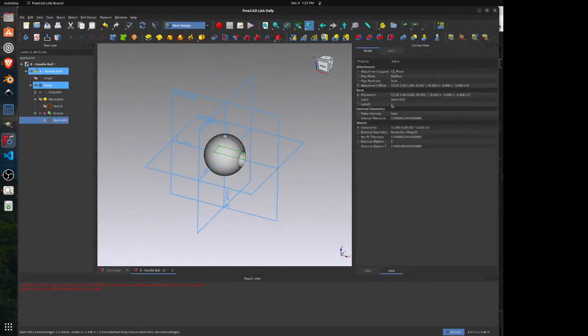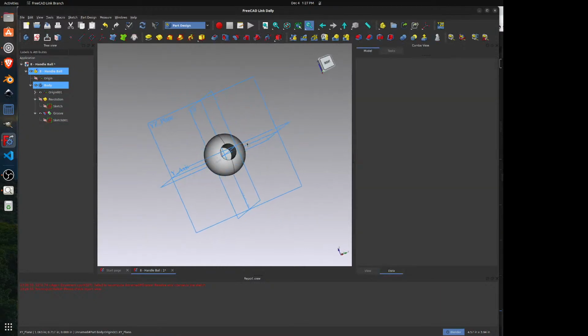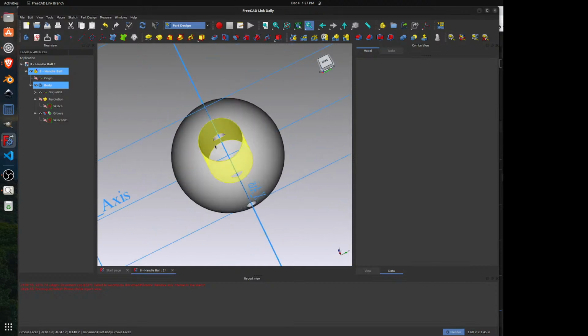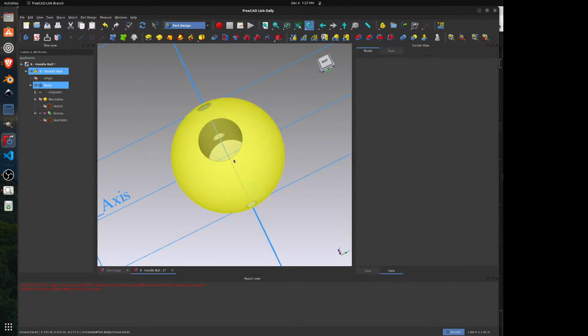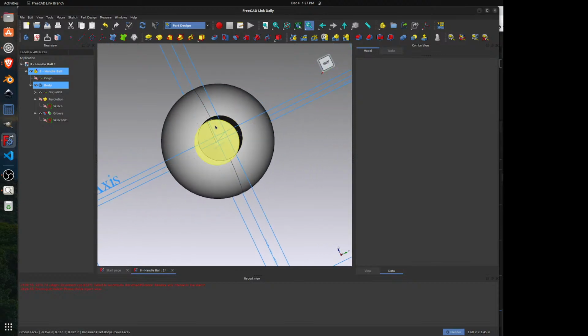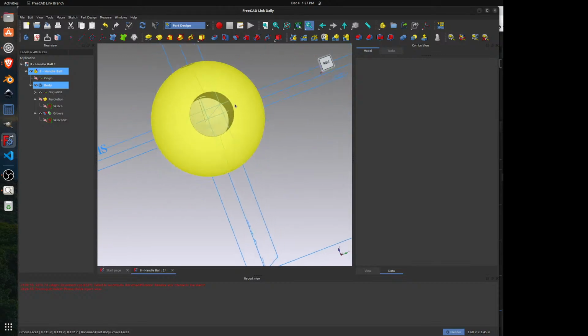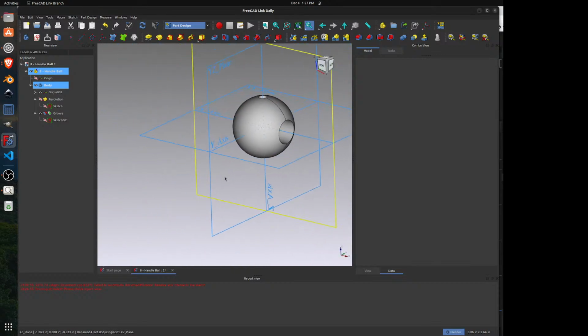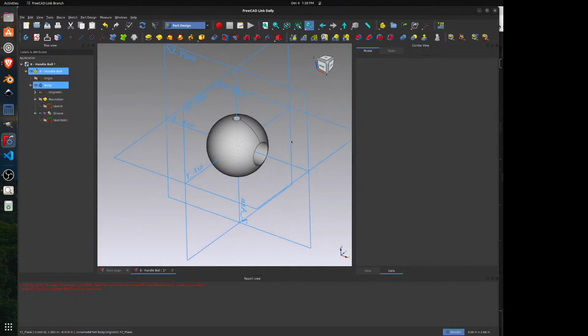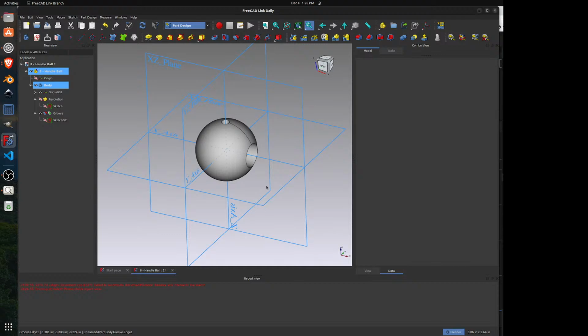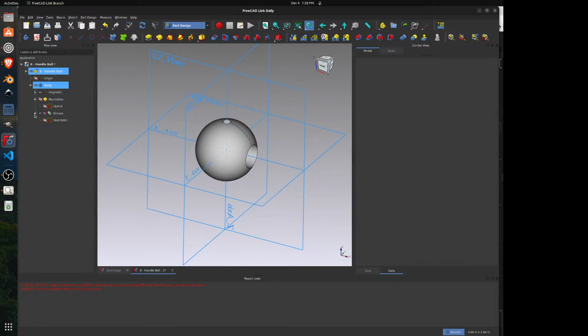And now when I come back and look at this, before, my hole diameter didn't clear the tapered cross hole in there when I was specifying the depth to the point of the drill. And now it totally clears it. So I think that is actually a more correct interpretation of that dimension. And in my day job, that's how we actually define our hole depths. We specify on the drawing that all of our hole depths are of the full hole diameter. So that way there's no confusion.